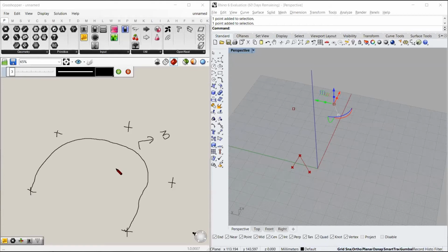By mathematical function, to create the smoothest and most flexible curve, the degree is always set to 3. If you don't set the degree to 3, suppose I change the degree to 1, the flexibility and smoothness becomes 1, and the curve would be something like this.